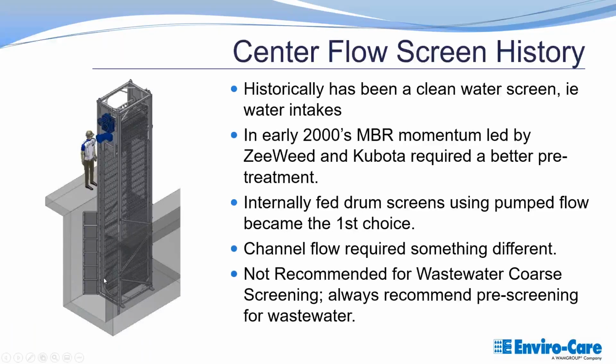The primary downside to this as a coarse protection screen is any larger debris that comes into this has to be able to be lifted up by those lifting fingers that are used to pick up the debris and deposit it. Anything larger, picture a bowling ball, for example, but any debris of that nature could work. As that comes in, the lifting fingers will try to lift it up, it'll fall back down, and then it will land directly on these panels. You'll see a lot of these style screens end up with dented or broken panels as a result when they're used for coarse screening protection. So while they can be used for coarse screening protection, it's not a recommended application when you have some of the other options available that would be better suited.